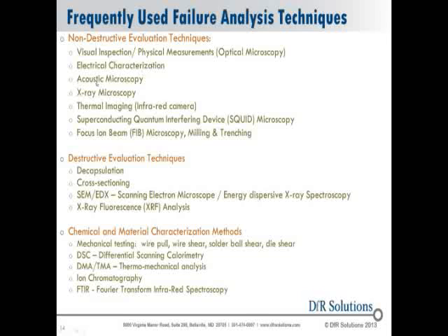There is an ultrasonic acoustic microscope, X-ray microscope, infrared thermal imaging, a rather new technology called the Superconducting Quantum Interference Device, or the SQUID microscope for short. And there's also the focused ion beam microscope, which allows you to mill and trench components in order to cut into them in very, very fine locations.